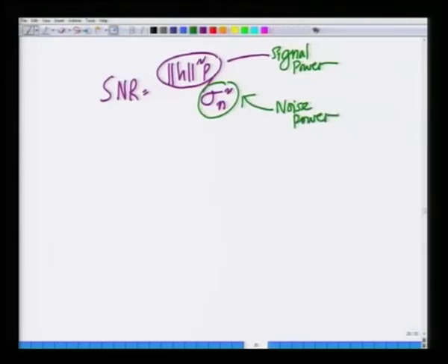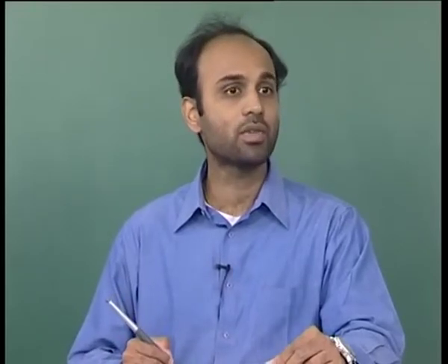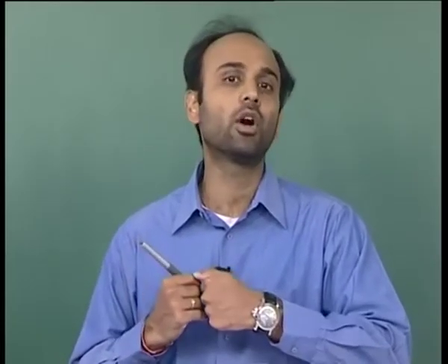And we said the system is in a deep fade when the received power is smaller than the noise power. Remember, in the wireless fading channel case, the system is in a deep fade when the destructive interference is such that the received power at the output is smaller than the noise power.